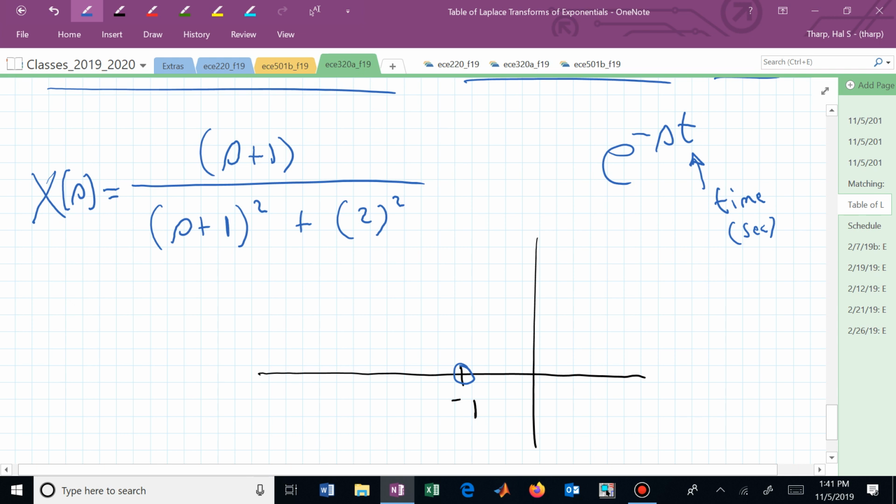The exponent needs to be dimensionless. S now has units of per time or per second, and typically we have this having units of radians per second, where radians is dimensionless. But S is a frequency. We'll say, what's our complex frequencies? Where are the poles? So S is now, the poles have units of radians per second. That answer your question?